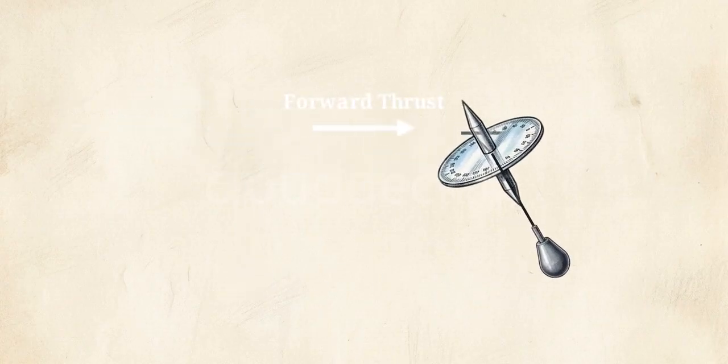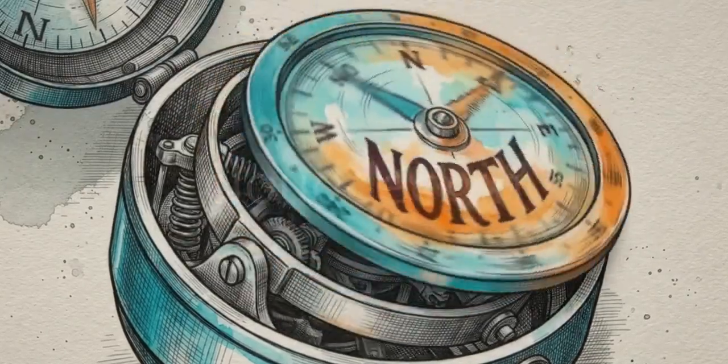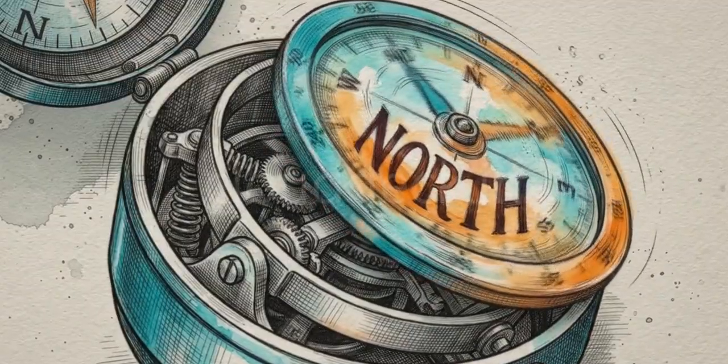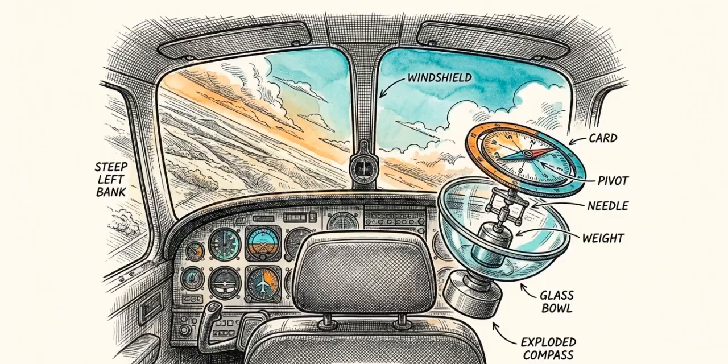When an aircraft accelerates on an east or west heading, the physical inertia tilts the pendulum backward. The compass card rotates, registering a completely false turn toward the north. Decelerate, and it registers a false turn to the south. Banked turns trigger a different physical lie.